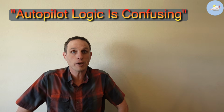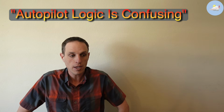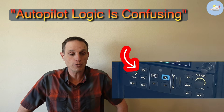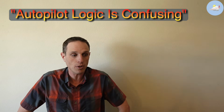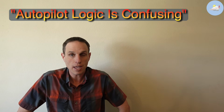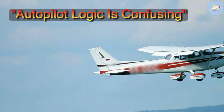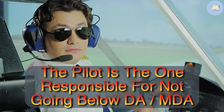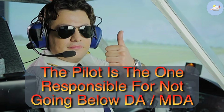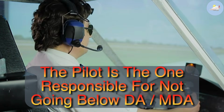And lastly, a lot of people are arguing that autopilot logic is confusing. Sorry to beat a dead horse here, but Garmin has been consistent. In approach mode, where the plane is following a glide path, it's going to do that indefinitely until you manually change pitch modes. And this is the same whether you're flying a $50 million Gulfstream or a $50,000 Cessna 172. The pilot is the one responsible for not going below decision altitude or minimum descent altitude.